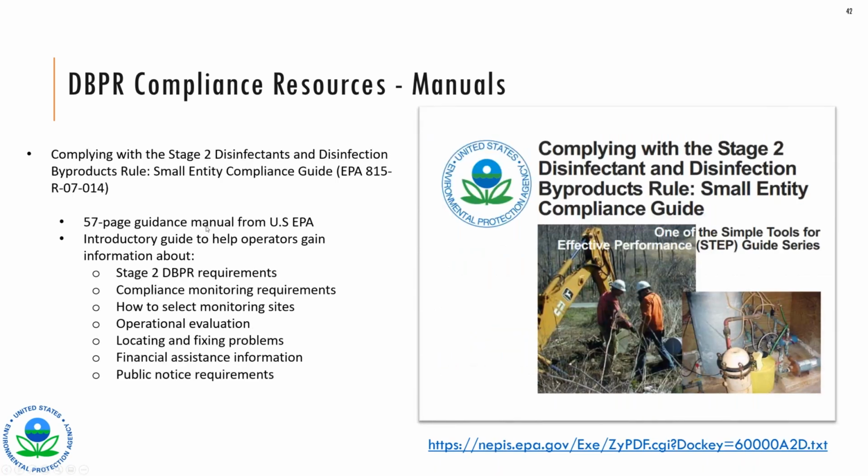This is the Stage 2 DBPR Guidance Manual for small systems, which is similar to the one that I mentioned previously, but for Stage 2. This is also from the EPA. It's a 57-page guidance manual, and it provides an outline of the Stage 2 requirements. So it'll outline the compliance monitoring requirements, how to select monitoring sites, how to develop a compliance monitoring plan, how to calculate your operational evaluation level, and tips for those that are performing an evaluation to locate and fix problems.